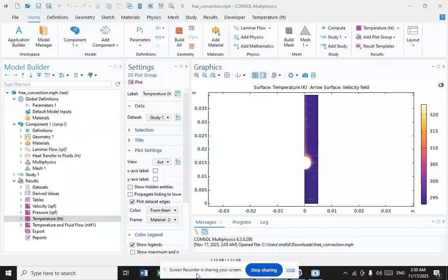It is shown that natural convection boundary layer has a unique turbulent structure which is rarely seen in other turbulent boundary layers. The results suggest that for values of y plus between 20 to 100, it is not correlated with the mean velocity gradient. However, comparison of Reynolds shear stress with previous experiments showed a different behavior near the wall. Although no negative region was observed by Nagano in 1988, almost all previous works have shown a negative region close to the wall.